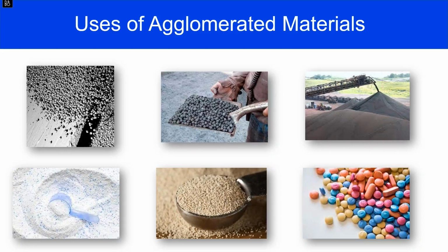Now, what they were digging up is these big chunks and granules and putting them in a blast furnace. It worked just fine. They put in this purified material, and because the particle size was so low, you couldn't force CO through the system and reduce the iron. And so they went back to the drawing board, and they actually granulated the iron and made these pellets. In Minnesota, we call them taconite pellets. I think the rest of the world uses this now, and they'll just call them iron ore pellets.